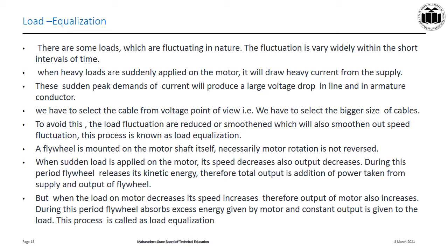On the other hand, when the load on the motor decreases, its speed increases. Therefore, the output of the motor also increases. During this period, the flywheel absorbs the excess energy given by the motor, and a constant output is given to the load. This complete process is known as load equalization.